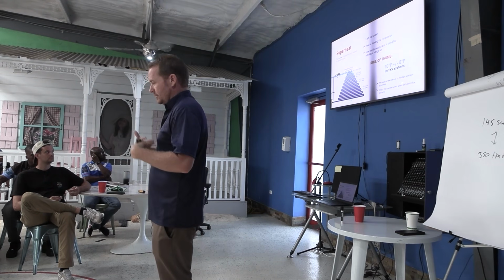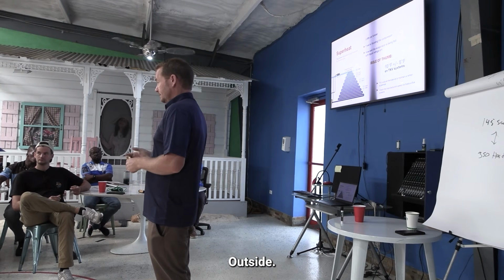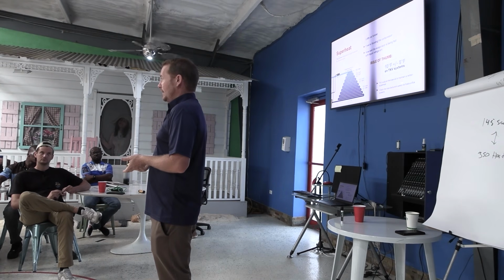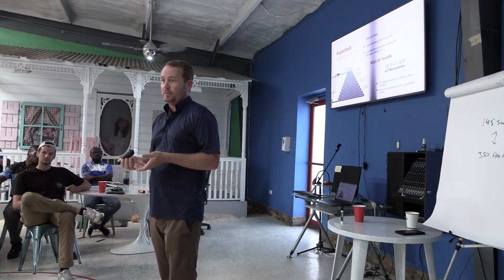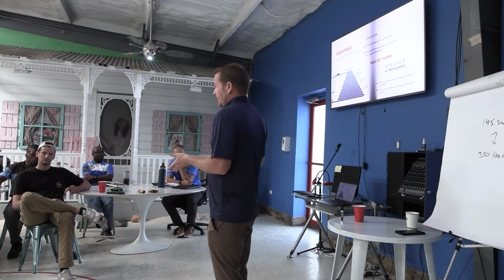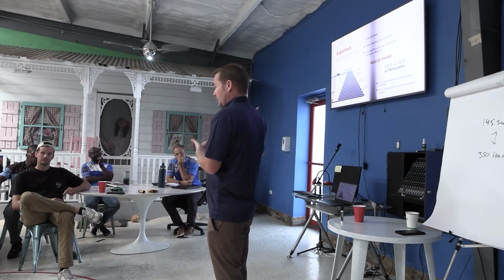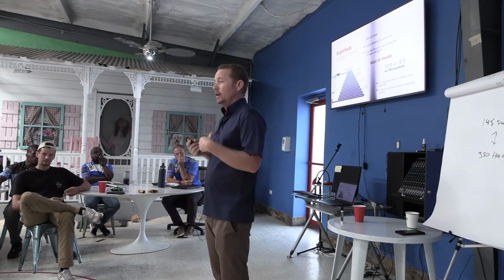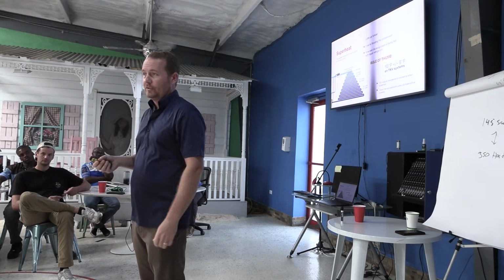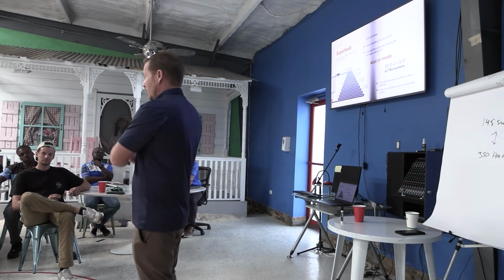Because where do we measure superheat? Where do we typically measure it? We measure it outside, right? Is that what we're actually trying to find out, what our superheat is outside? Where do we care about what our superheat is? Right, we care about fullness at the evaporator coil. We care how full it is at the evaporator coil. So if it's a 150-foot line set and somebody didn't insulate it and ran it underground for 20 feet, that really tells us nothing at that point about what's going on at the evaporator coil.